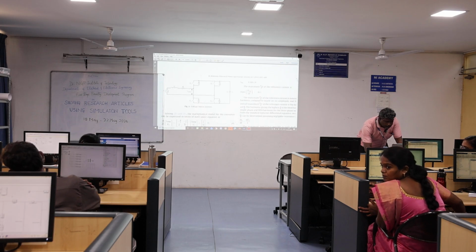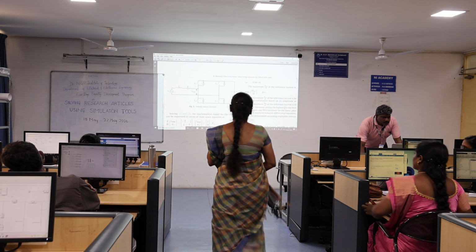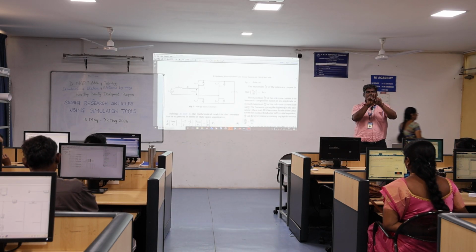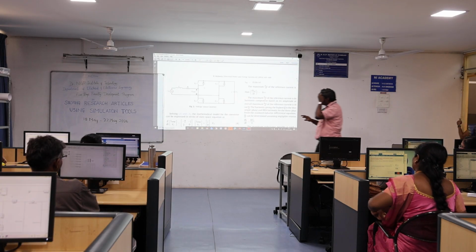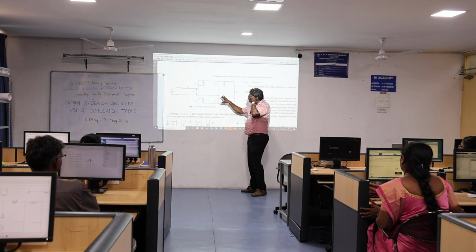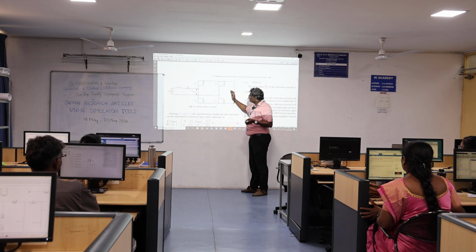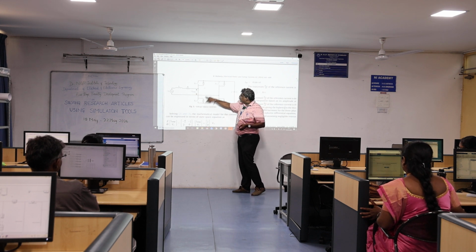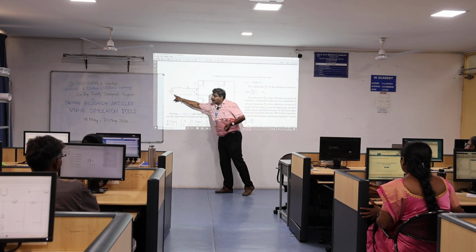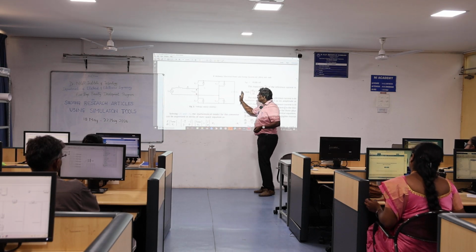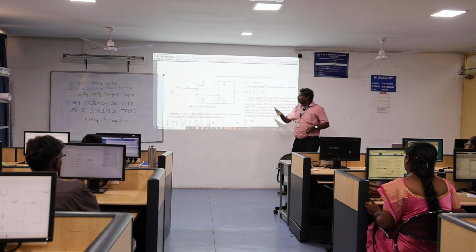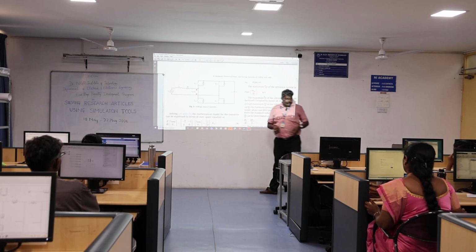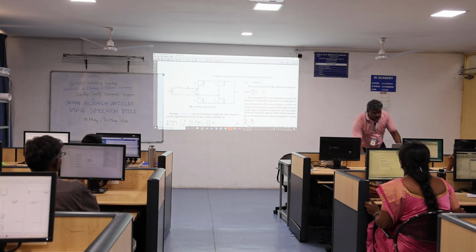This is the normal voltage source inverter. In the previous block diagram, you have the voltage source inverter as one single block. Inside, you have a single phase voltage source inverter. We need to provide a constant voltage; S1 and S2 operate in one mode, then in another mode these two are operated. Again, it is connected to the line, right? So this is the single phase inverter. We have to construct this circuit, take feedback, and also design the PI controllers.